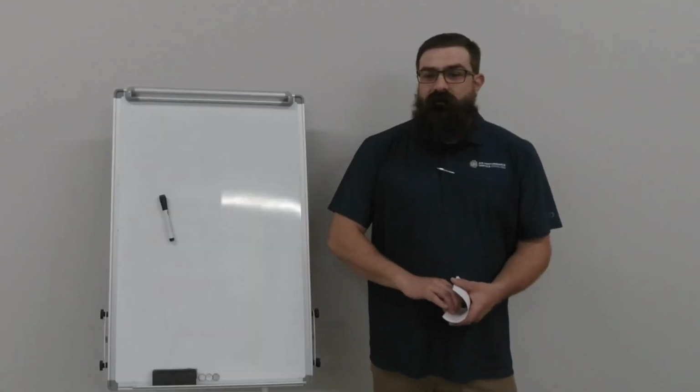So say you have a fan coil unit, it has 1 coil in it with 1 valve, and we have a changeover temperature outside. So if it is hotter than say 65 degrees outside, it opens up to a chiller. If it's colder than 65 outside, it opens up to a boiler, and that valve changes operation based on your temperature. So your air handler can heat and it can cool both with the same coil. 2 pipes are very rare nowadays.